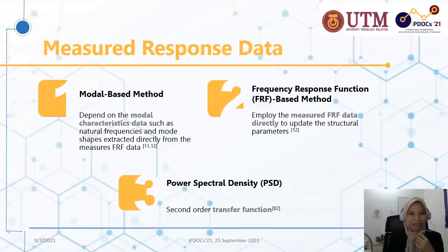Several studies have examined the structural response for model updating, especially the modal-based and frequency response function-based. The modal-based model updating methods depend on the modal characteristic data, such as natural frequencies and mode shapes extracted directly from the measured FRF data.